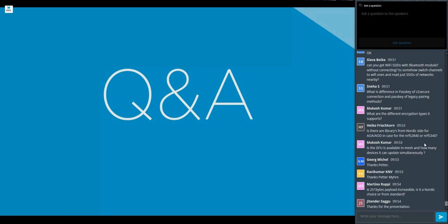Are the data rates mentioned maximum rates for 20 simultaneous connections or just one connection? Can all 20 connections run at 1400 kilobit per second? All of these numbers are for one connection, and if you have more connections, you have to split this throughput between the devices. Because when you run at full throughput, you are using the full radio time.